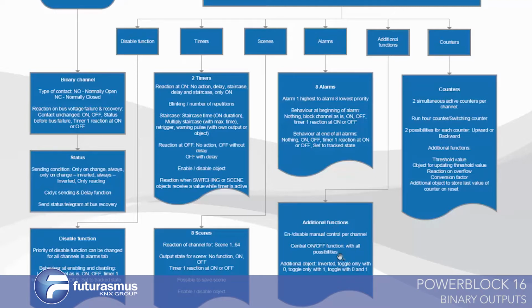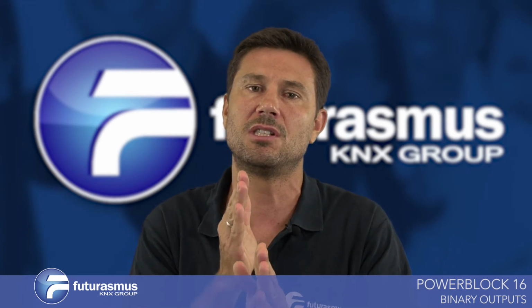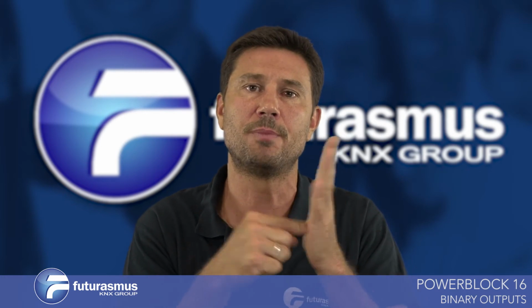There are also some very interesting things like the toggle function. No KNX actuator which I know of has the possibility to receive a telegram telling it to toggle, because the toggle function usually is in the push button.